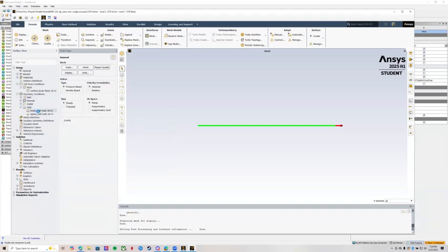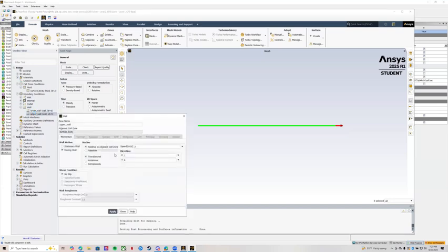And then we're going to go to our upper wall, which should be the moving wall. We're going to change that velocity from 2 to 0.4. Our total velocity between the two plates should be 1.2. With those values and our viscosity of 1e-4 and the density of 1, we should get a Reynolds number around 100. That's the round number we calculated for with the dimensions of the 750 millimeters and the 5 millimeter height. So we're going to apply that.